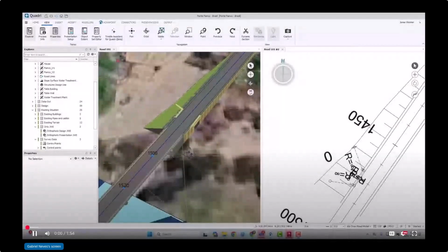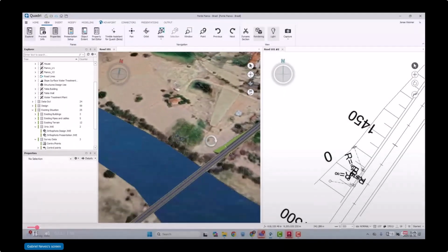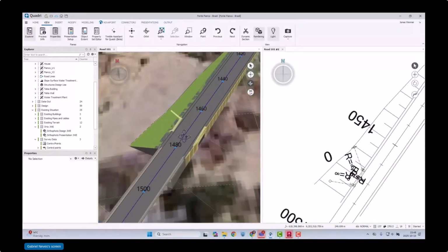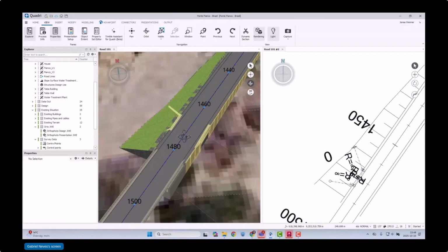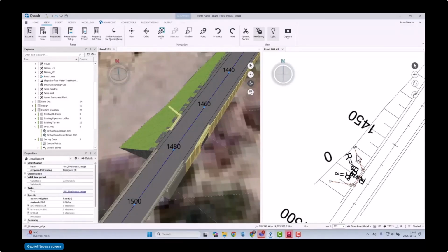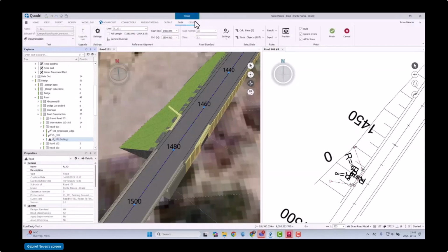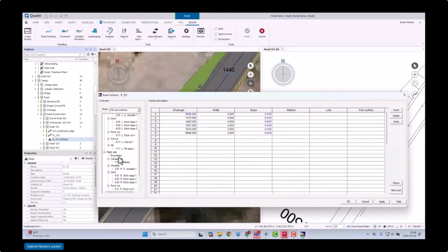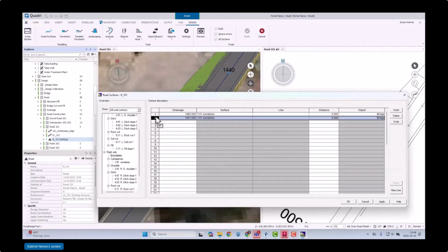Editing road design, Jonas. Yeah, so what we didn't show you first was the basic road design that we did before Gabriel started modeling the bridge, but now he is modeling the bridge and the underpass. And what I do here in the road design software is that I use his models, and then with some simple means we create sort of an alignment on top of this underpass, for example. And then the road modeling software we use here, NovaPoint Road, is a parametric software, so we can just add this alignment we have created, that is then the top of the underpass wing walls there.